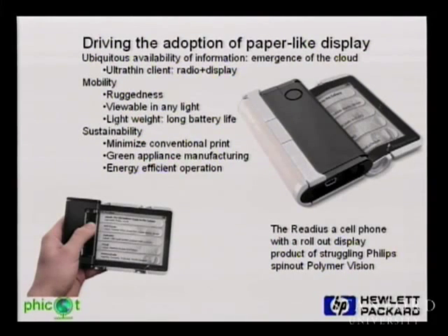What constitutes a page-like display there? I mean, a Kindle's just another LCD. A Kindle's not an LCD. A Kindle has an electrophoretic front plane. It's a very different display technology. It's reflective. It's not backlit. Today, the problem with a Kindle is that it's built on top of an active matrix backplane that's on a piece of glass. And it's married to glass, but it in itself is a piece of plastic. And in fact, we've built the world's first roll-to-roll displays, and we've used that same e-ink front plane for those. So e-ink, there's nothing wrong with in itself for plastic displays, but to date, there really isn't a good backplane technology that matches that.